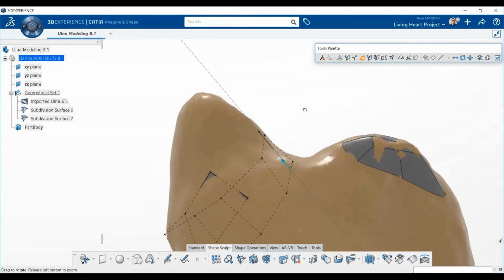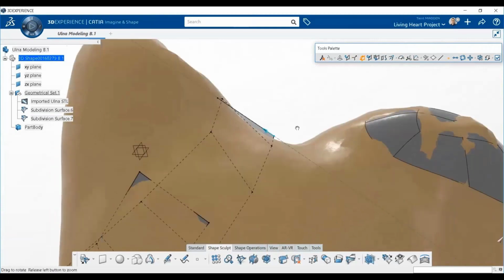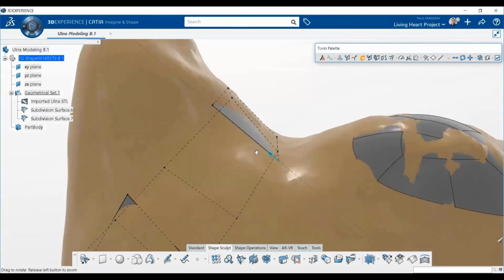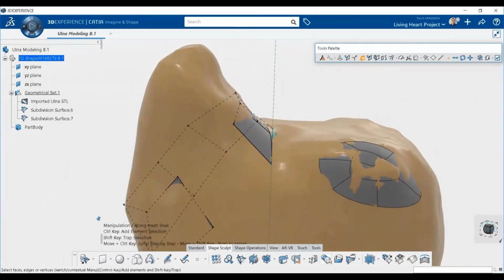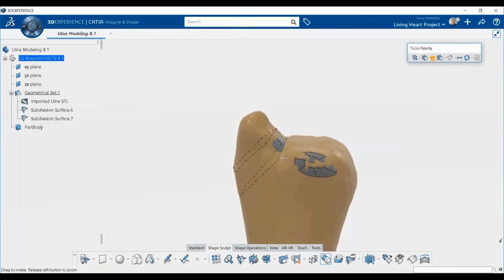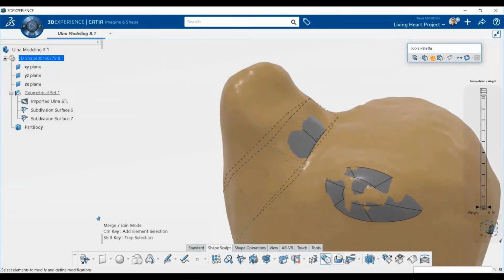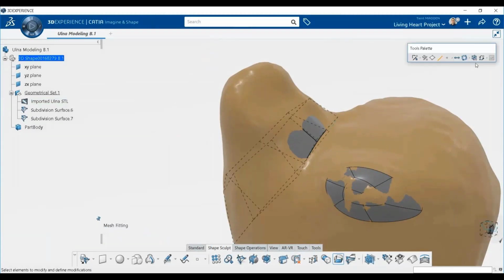Generally when you auto surface, it doesn't quite know what areas of the surface need less data, or what areas need more patches to fit better, right? When you manually define it, you can explicitly control it: I only need 10 or 12 patches to represent the shape of this process. I don't need any more than that, and any more than that is just wasting your time trying to manipulate all those nodes around.